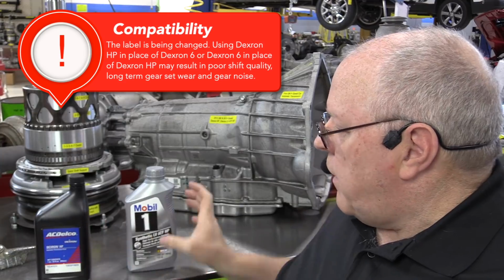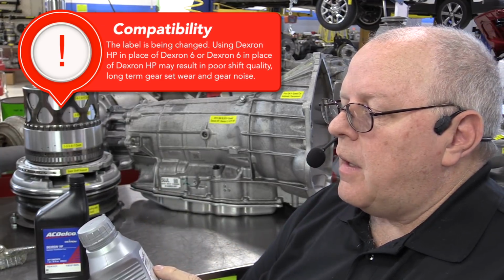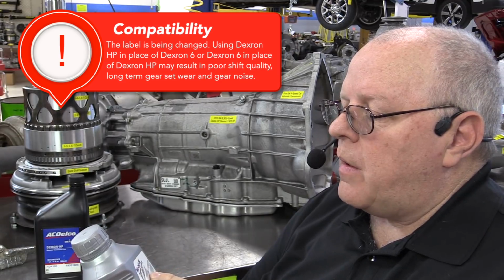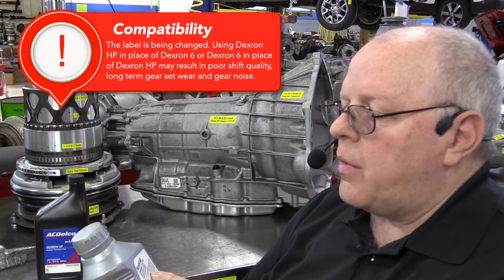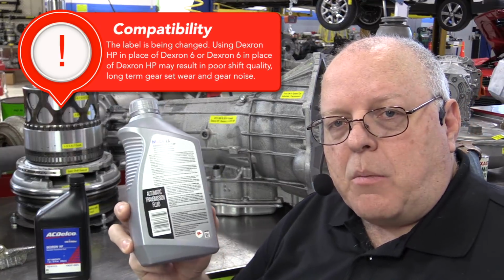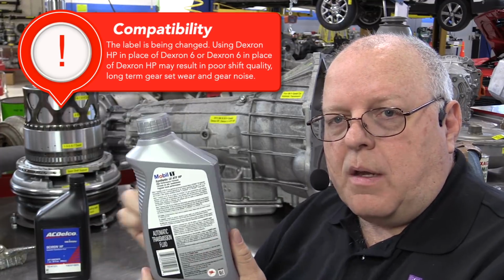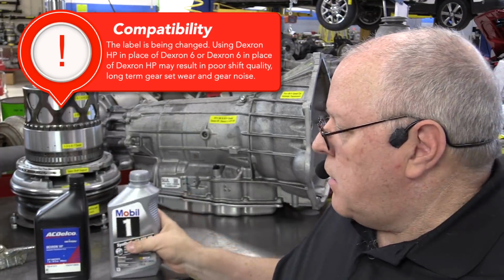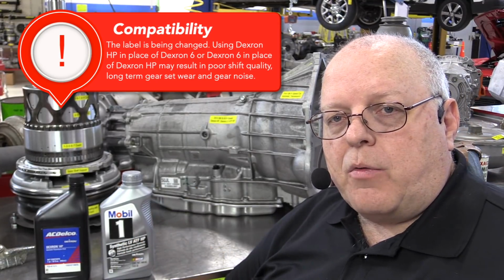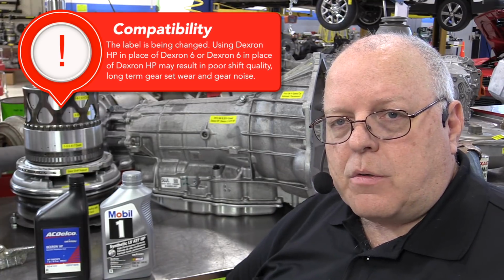Even the Mobil 1 fluid says that it can be used with vehicles specifying Dexron 6, 2, or 3 type fluids. Well, there's a service bulletin from General Motors saying that is incorrect. Only use this in the 8-speed transmission and other transmissions that it may be called for, and that it is not compatible with the previous versions.